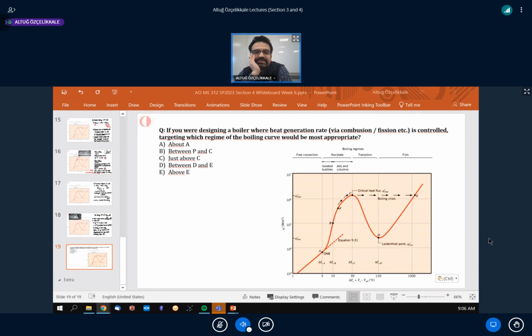Remember Nukiyama's experiments. I'm also seeing the same pattern in the reboot session. I can see the answers here. So what was the problem in Nukiyama's experiment? It's easier for you to reply, guys. Anyone remember what the main problem is? Yes, the jump, right? This boiling crisis, exactly. So this jump melted away his specimens. Iron melted, nichrome melted, any metal without an excessively high melting point is going to melt down. So you don't want to be there.